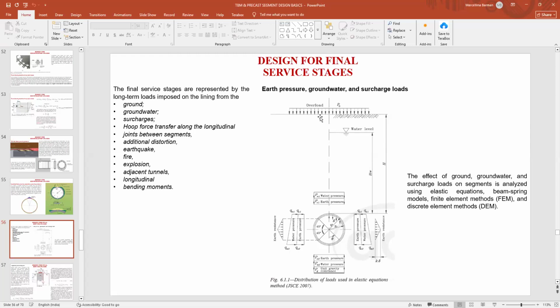There will also be a fire load, and fire loads are very important nowadays because all your segments need to be fireproof, or whatever segment thickness you are providing needs to be compatible with the fire guidance. So if it is a 275 mm thickness, or a 350 mm thickness, it needs to take into account the fire load, the temperature that will be generated, and the amount of heat energy that will be generated in joules. That will determine the segment thickness that will be affected, but the balance thickness that will be left will take into account the design life of the segment.